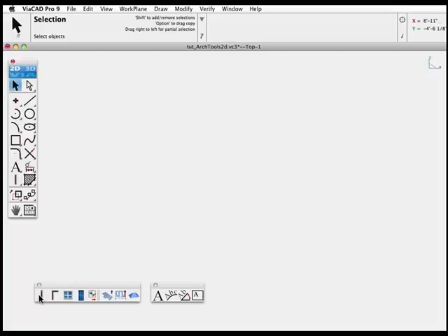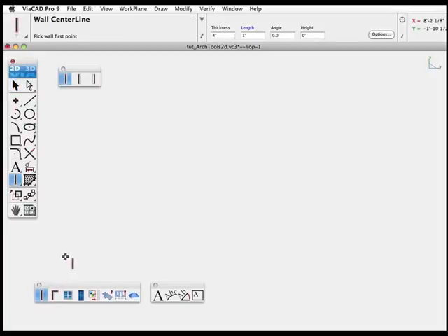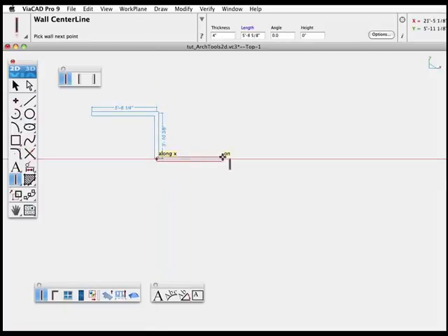The architectural tools are provided to help you draw architectural drawings and sketches. Walls are drawn as a special entity type with an actual scaled width or thickness. To use this single wall tool, pick 2 points as a starting point and an ending point for each wall segment. You can also click and drag to the end of the wall.